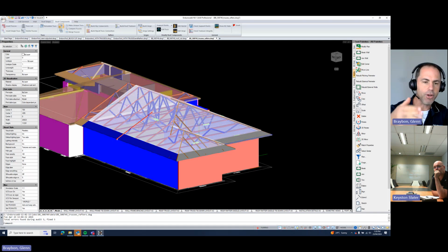Luckily, Tom picks that up and he can fix it before it gets to the machine. He sorts it out before then. But there's one thing I noticed the other day. There was a job where all the webs were detailed in 0.55 instead of 0.75, and it wouldn't roll. Whereas the HMI used to give you an error message and it'd let you proceed. Now apparently it won't.